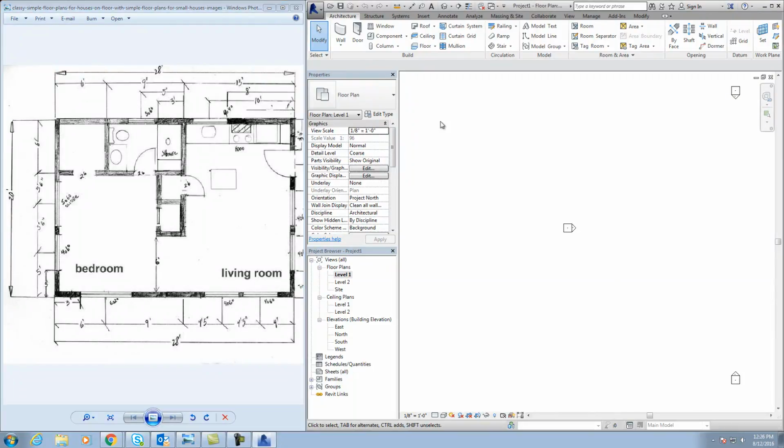And inside your Revit, again, you have different commands for viewing. If you've got a wheel on your mouse, you can just roll it back and forth to zoom. If you press your wheel down on your mouse, you can actually pan it over. If you don't have a wheel on your mouse, you've got the buttons right over here that you can do the same stuff with.